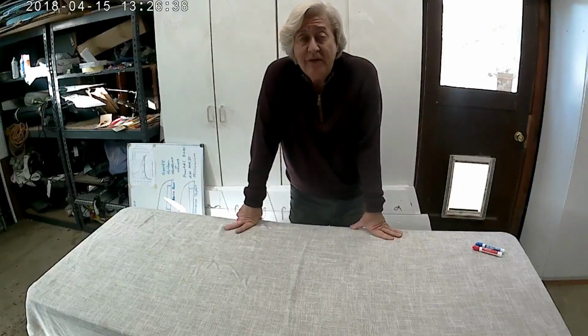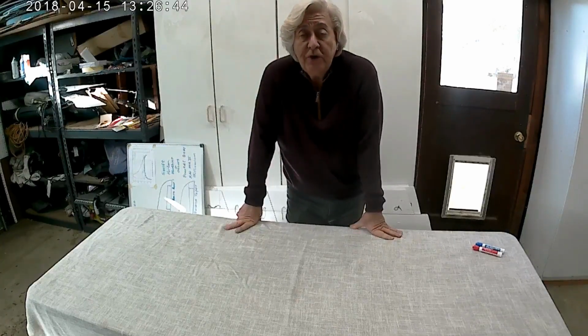So I went down the path of not having control surfaces out on my wingtips, and on the model it worked wonderfully. No matter what you did to it, you really had to force a spin, get the CG aft and force a spin to get it to spin. Other than that, it was very benign.